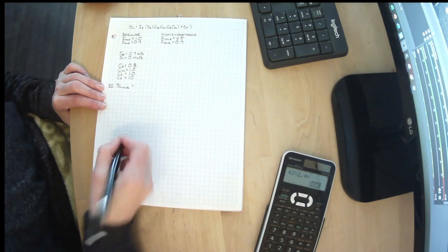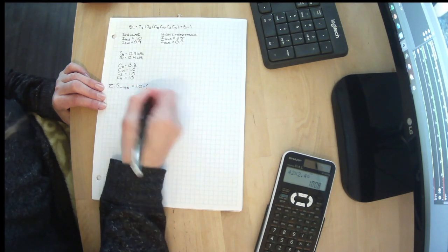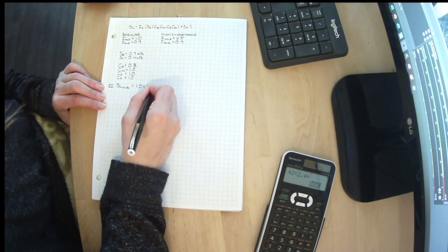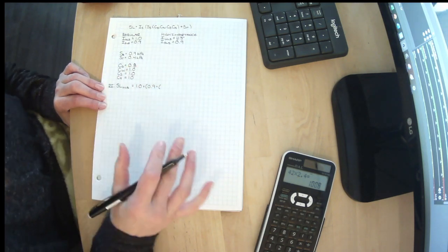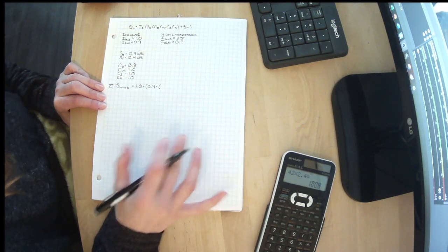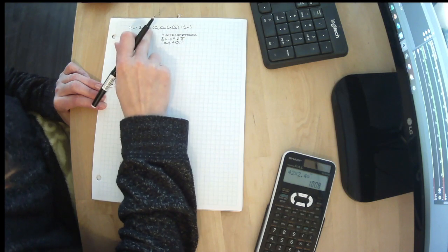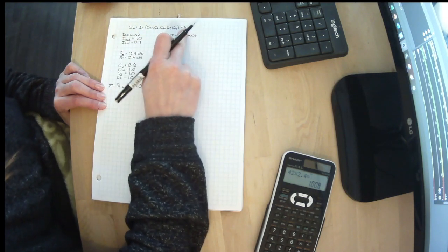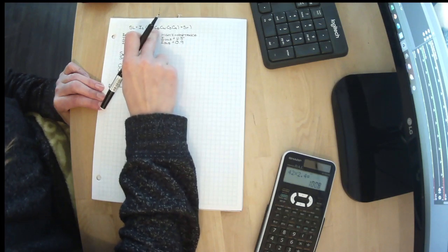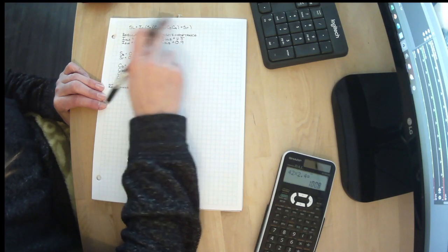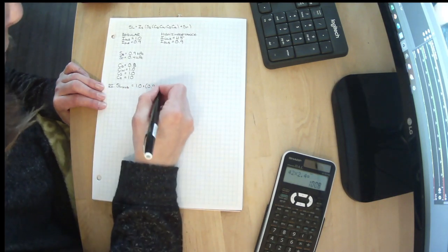Our snow load for strength would be 1 times, and then in the brackets, 0.9 times more brackets. And I'm going to tell you the bracket placement in this is the thing people screw up the most. People get confused by this being multiplied by SS and then SR being added over here. They'll often lump this all in, or they'll multiply these and add this and then multiply it by SS. So pay attention to your brackets here, people.